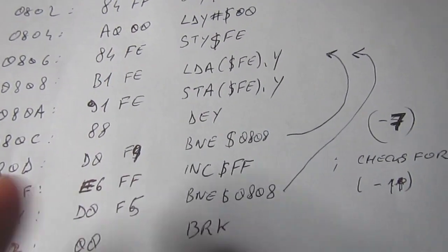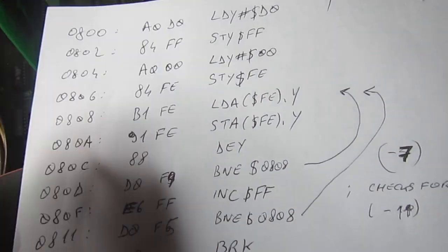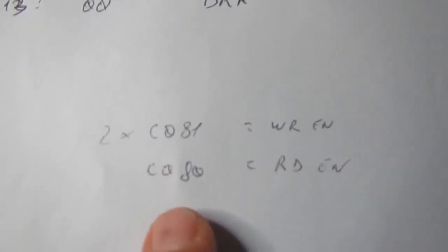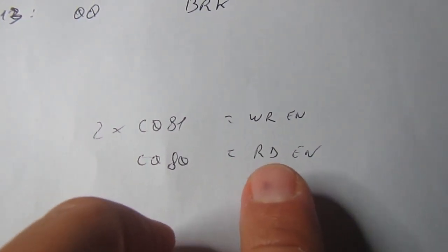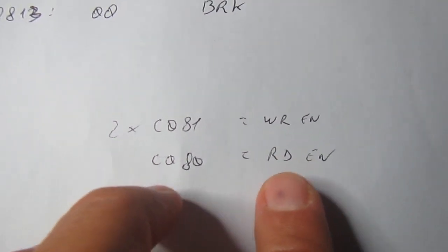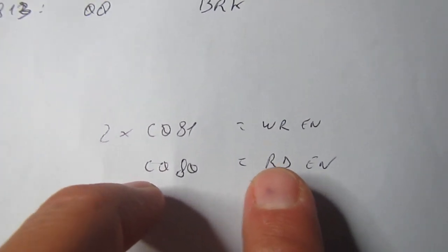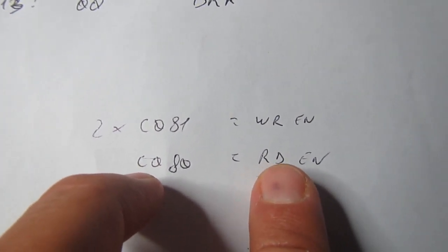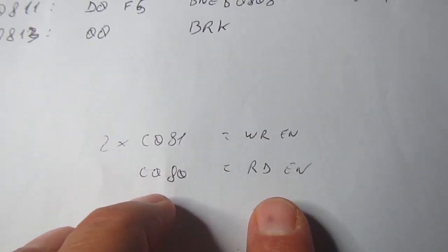We'll copy all the content of the ROMs to the expansion RAM, and after this reading from C080, the RAM will be enabled and the system will run from RAM, unless, as we have seen, if I enable the RAM without copying anything, the machine just crashes.